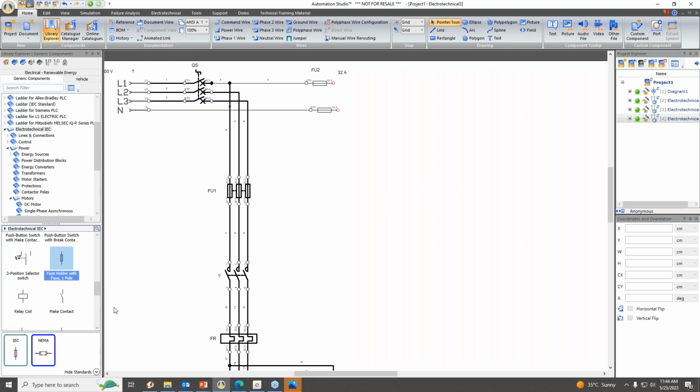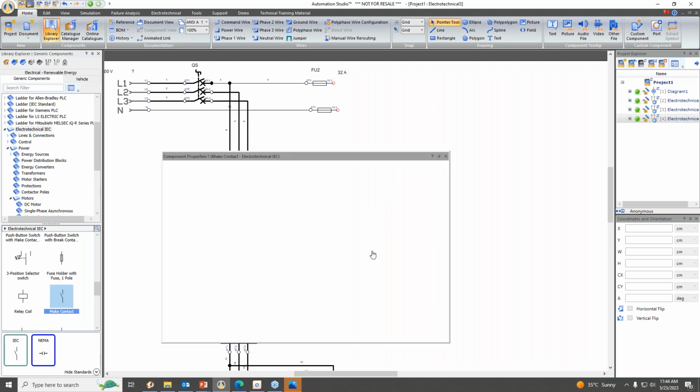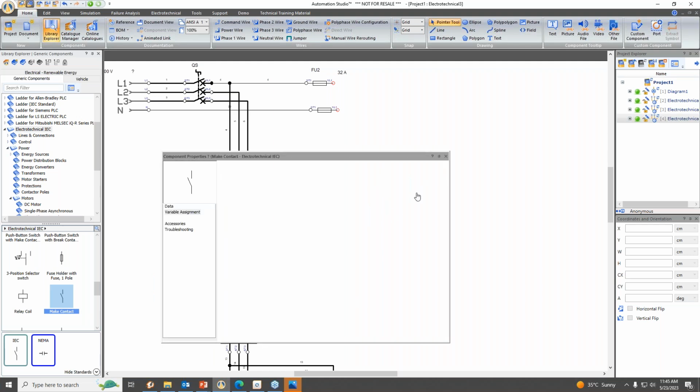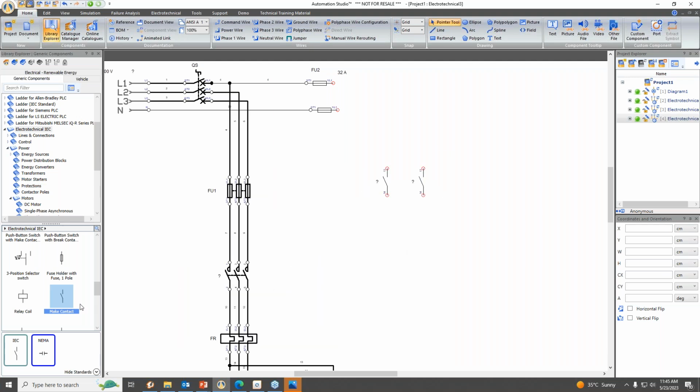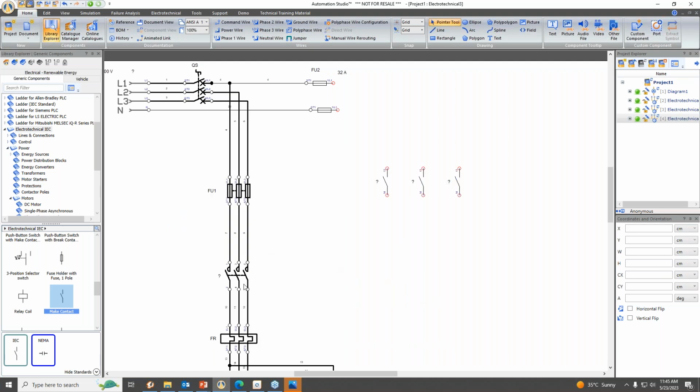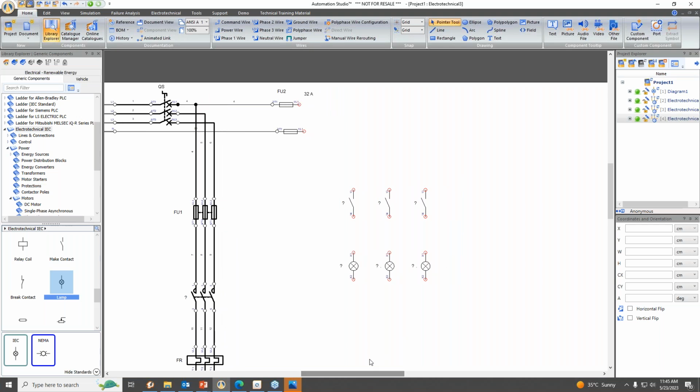Okay. So I'll require 3 make contacts. These make contacts we have to then variably link to the relay coils in order to activate this. And when we start the circuit, the lamp should ignite. So we will take 3 lamps for this. Now to control these 3 make contacts, 3 relay coils, and 3 lamps, we'll require switches.